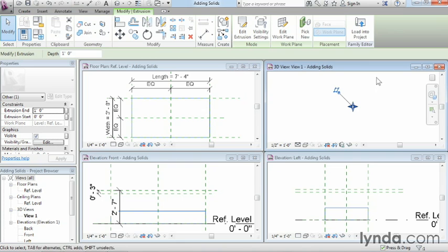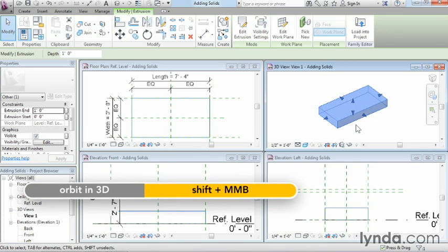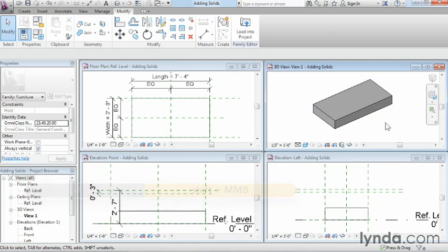And if I come over here to the 3D view and look at my little view cube here, if you can find the top corner of the view cube, you can click that, and it will zoom in on that object. You might want to go to the visual style and choose shading instead of wireframe, just to get a better look at this, and you can spin it around by holding down your shift key and dragging your wheel. Now, I'm going to deselect it, and what we'll, of course, notice here in the 3 different views that show it vertically is that it's a big, thick slab and it's sitting on the floor, okay?